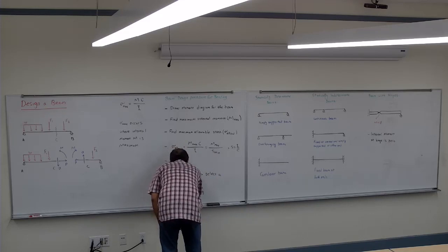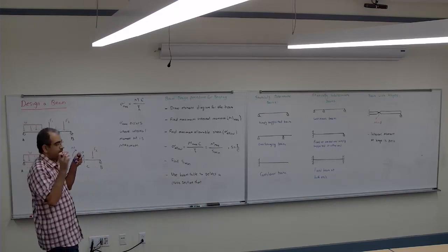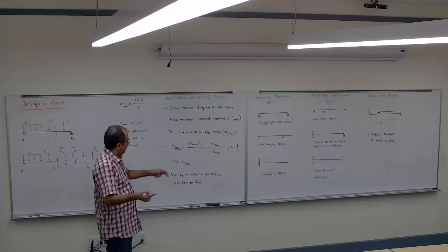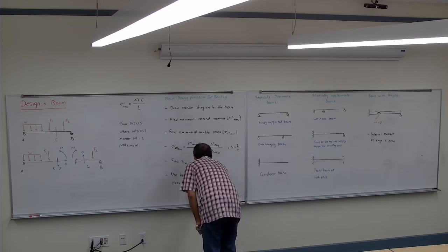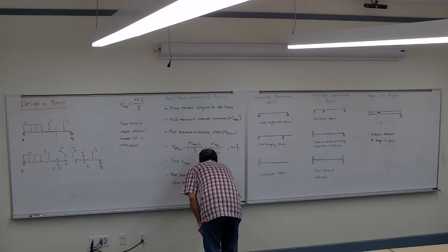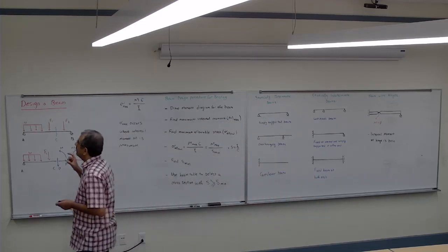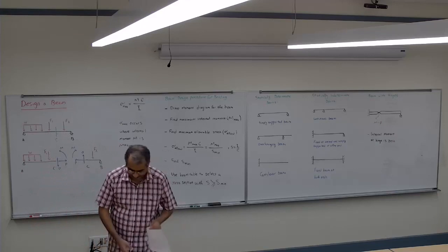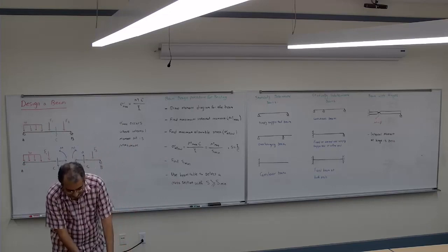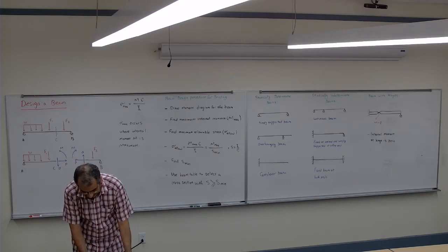Select the section whose S is equal or larger than the S min of the beam. Some samples of those tables we'll work with later on, at the very back of the book. We'll look into them later on.